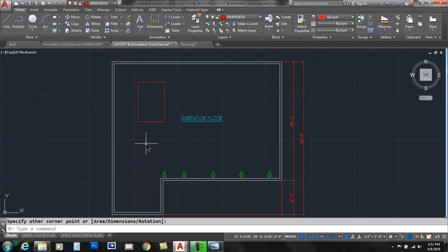Okay, let's say that is a hole in the floor, whether it be for an elevator shaft or a void looking into the basement or the floor below, whatever. Point is, that should not be counted as square footage. So here's what we would do differently. It sounds almost like the opposite, but in order for us to subtract the area of that void, we have to begin with an add mode.